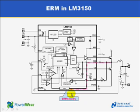Let's have a quick look at the emulated ripple mode circuitry in the IC. It is located here. It detects the voltage across the low side MOSFET. This voltage is added to the internal voltage reference and fed into the error comparator and compared to the voltage at the feedback pin coming from the resistive divider from the VOUT, the VOUT across the output capacitor having no ESR.